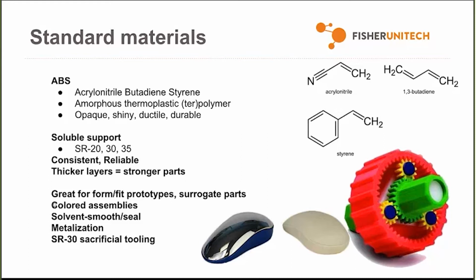Or you can use it to validate machining operations. If you're testing a machining operation on an aluminum part, substitute plastic instead. It's probably okay if the cutter runs into your part, or go take it one step further and 3D print the cutter. You can even design in a shear point so that it cracks off. That way you don't risk damage to your parts, and you don't risk damage to your equipment.